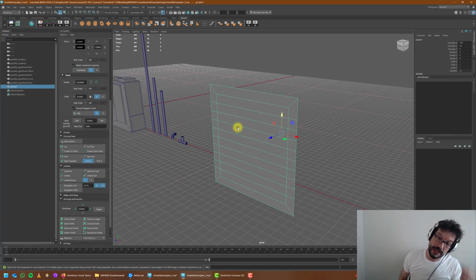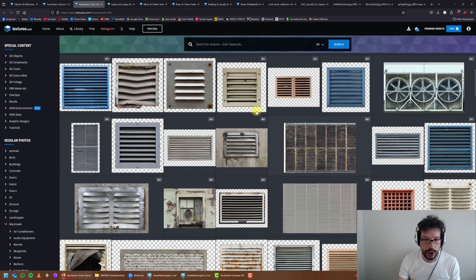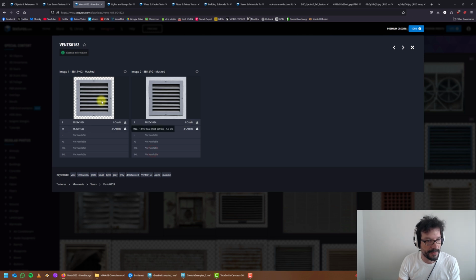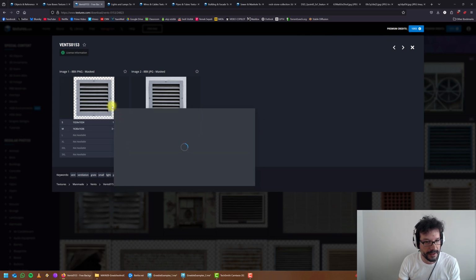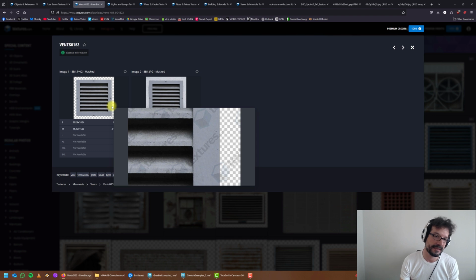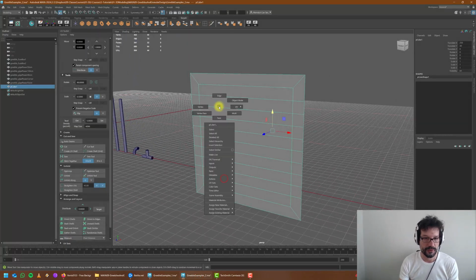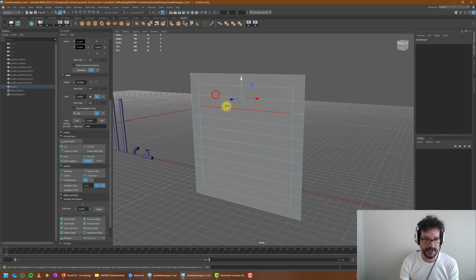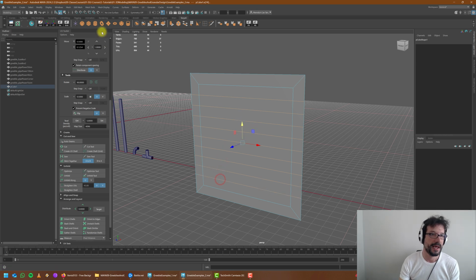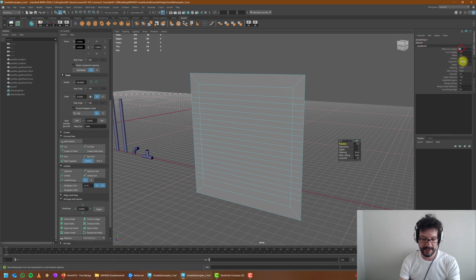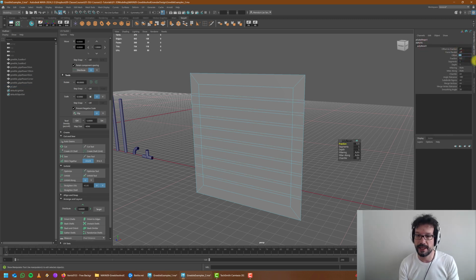Now obviously you can add more details. If you look, the grates themselves have flat faces. What I mean by that is they have flat faces in front of them. It is not fully sharp. You can do that if you want to, but you don't need to. And a good way of doing that is you grab all of these edges, okay, and simply say bevel,